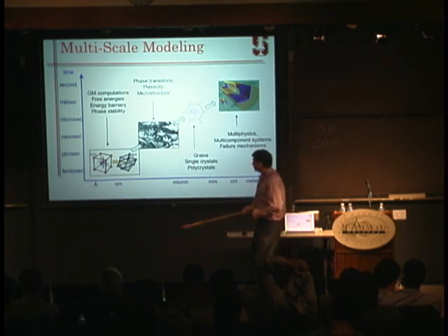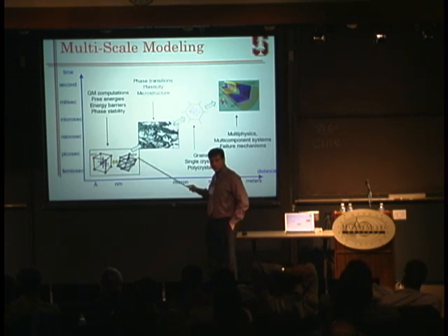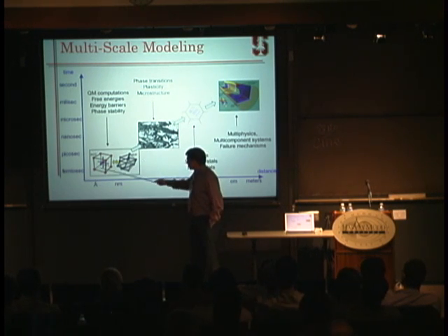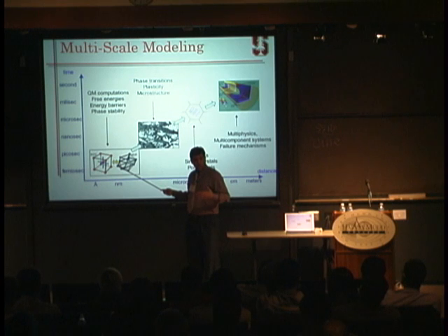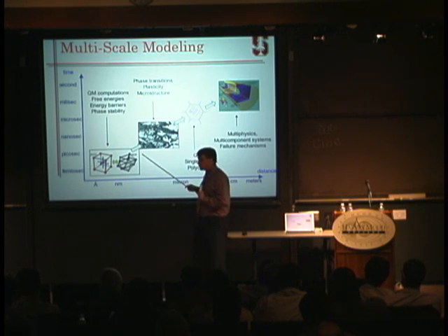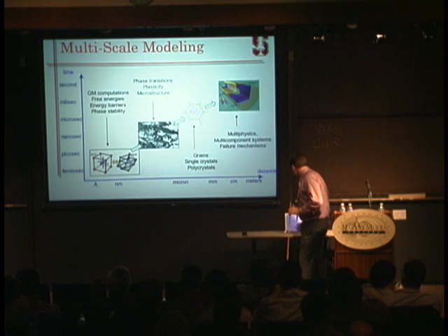So what we're going to focus now on is on these two parts. In fact, given the audience, I'm only going to focus on this part. I'm going to tell you a little bit about this one. So what we did is building our strain energy density, W of F, using quantum mechanics computation. Okay? And we use that to solve nonlinear elasticity problems, to find the type of microstructure that the material forms when you load it. Okay?